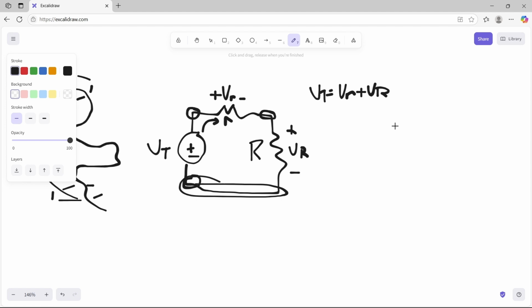And it kind of makes sense because, once again, the current has to flow somewhere. So if you think about the current coming out of the thermocouple through this first resistor, it's passing through this particular node. Well, if it's coming into the node, it has to exit the node somewhere. The only way it can exit is back through this little resistance. So suddenly that's how you generate V little r.